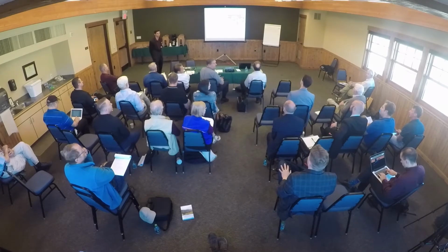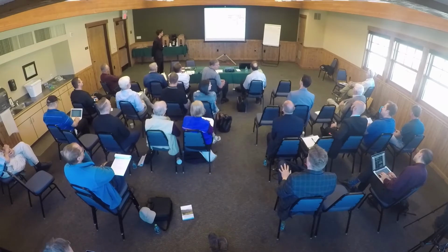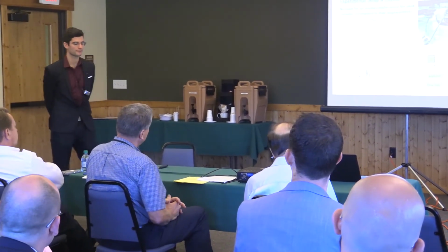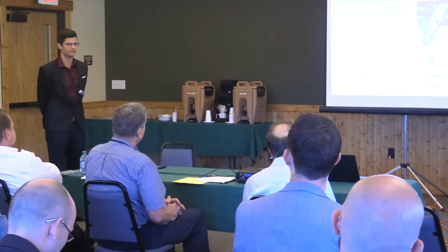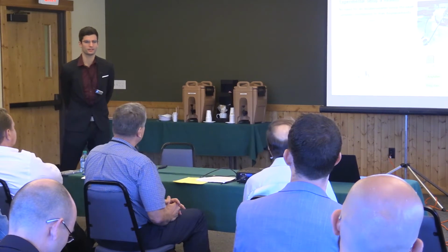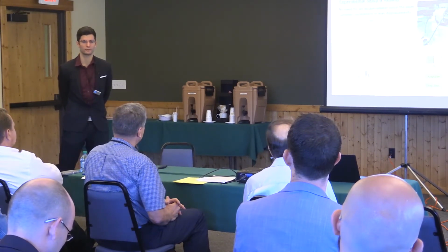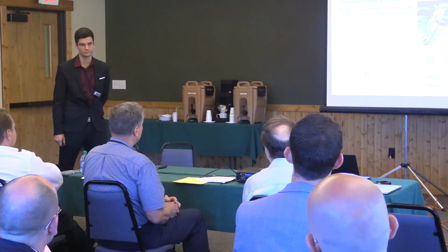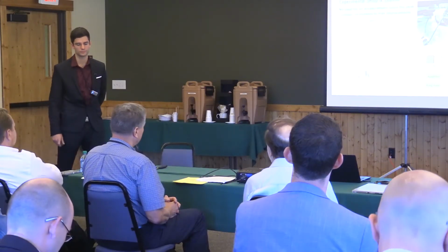Mike? I was just going to ask if you could comment on the higher displacement at 30 than 60 kilohertz, because I thought in your previous plot you had much higher power deposit at 60 than 30. Yep. Well, the way I see it is that it's the second harmonic, and usually the second harmonic shows a lower amplitude of vibration, just because it's a second mode, and then the overall displacement is not as big as the first mode, which is higher damping for higher modes usually.